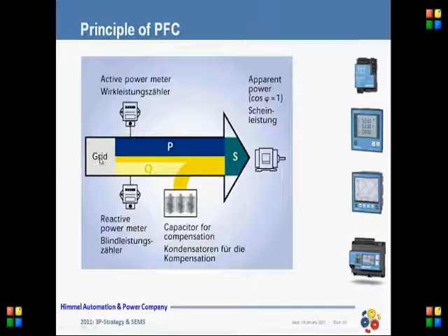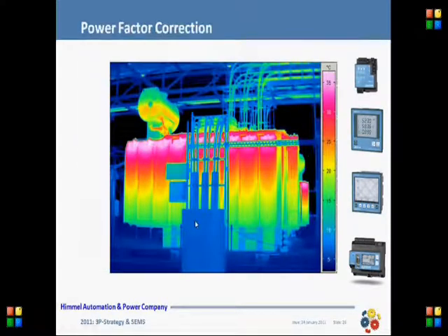So it is very essential, in fact recommended, to use the compensator capacitor banks. You can see, for example, the heating of the transformers in absence of reactive compensation techniques. All this heating means higher electricity bills if you own the transformer on your side.